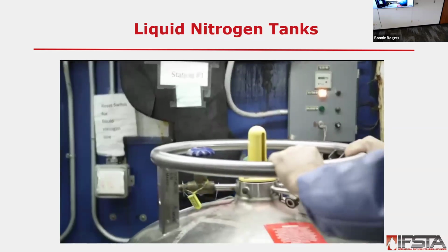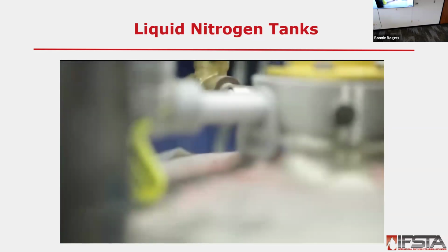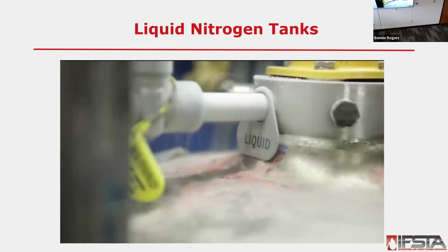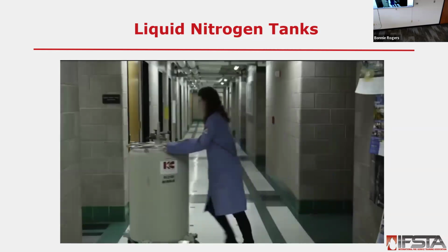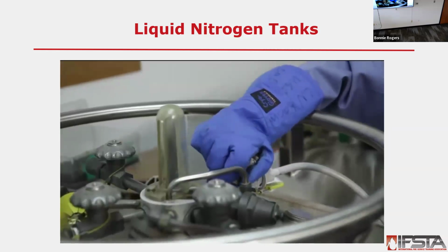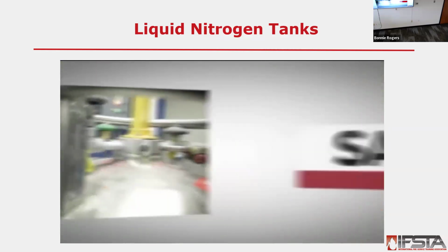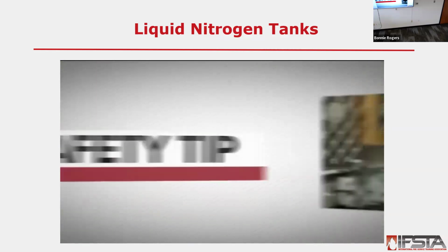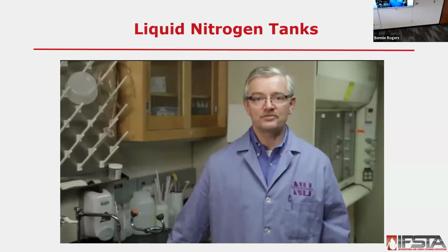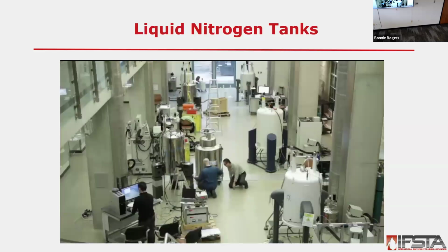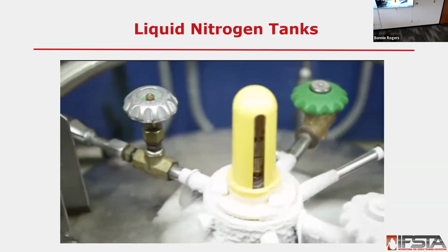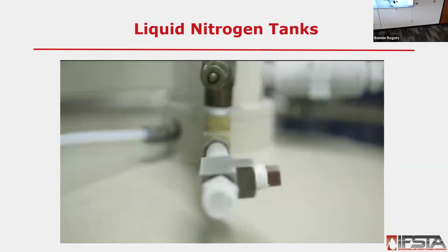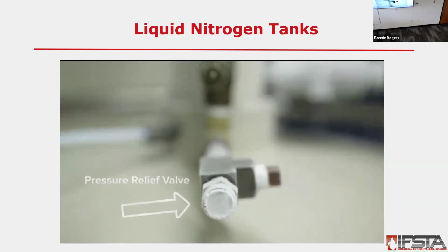These portable liquid nitrogen tanks are specifically designed so the liquid nitrogen is safely insulated to ensure users are well protected from the extreme cold during handling or transport, and the user can withdraw the contents either as liquid or as gas. If the cylinder is dented or damaged during transport or use, the tank must be professionally inspected to ensure it may continue to be used safely. Cylinders are equipped with pressure relief valves that will open and close to release gas at preset pressures.